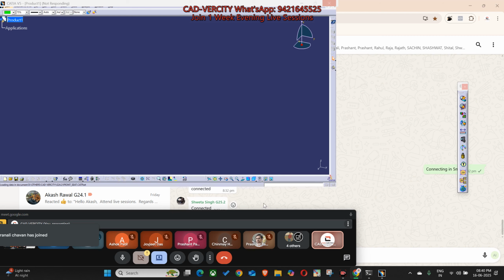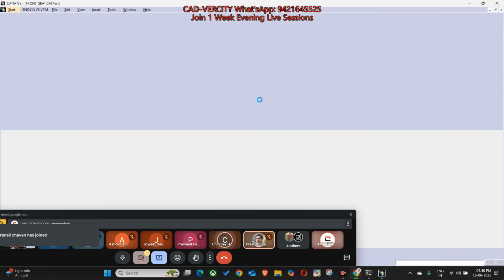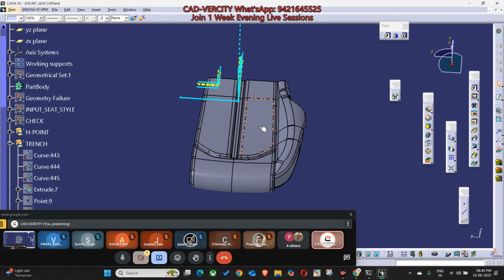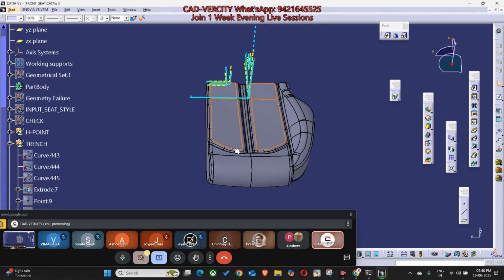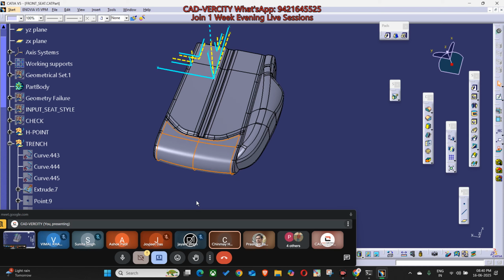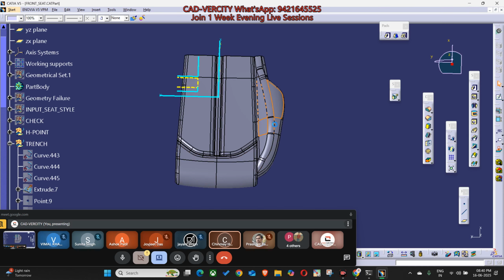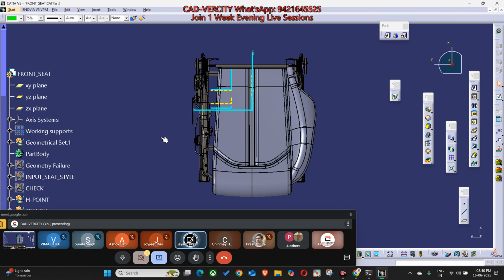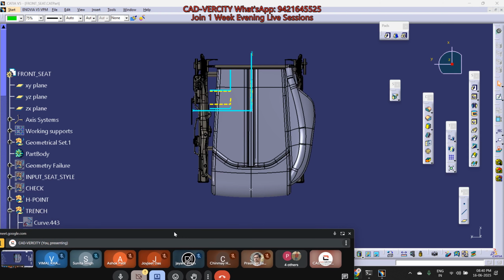What is the material for foam? PU, sir. What is PU? Polyurethane. Okay. What is this patch? We call it the front insert. And this one, bolster. Is it an IB bolster or OB bolster? If we check with the structure, IB. Why IB? Because it is the driver seat, sir. Okay, is it a driver or passenger? Suppose it is a non-Indian OEM car, then it's a passenger seat.